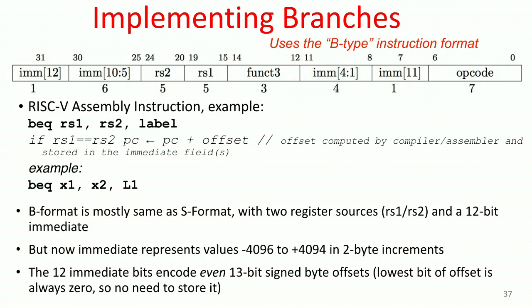So let's just say we're doing A equals B. So this will be A0 and B0, and this will be A1 and B1. Now, if they match in every position, so what XOR does, if they match, you're going to get zeros everywhere.